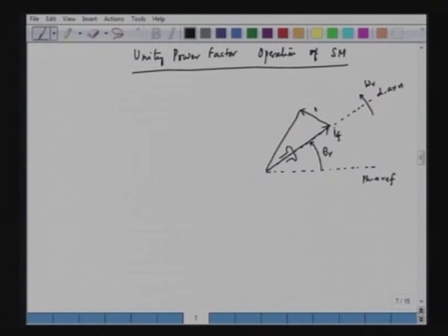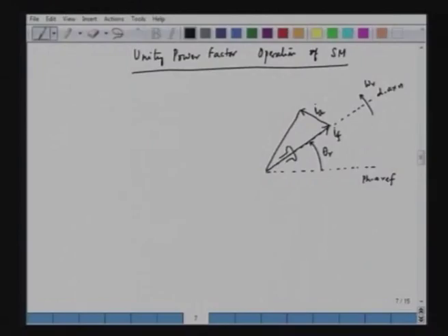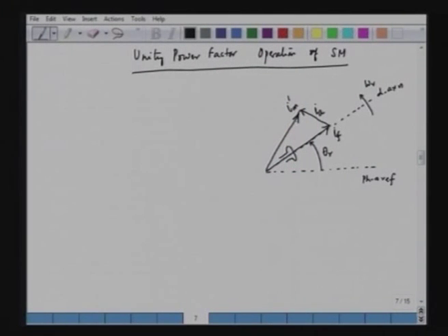This is armature current, we can call this IA, and the resultant of the field and the armature, in the machine we have two excitations, the field excitation and the armature excitation, is the resultant current, which we call the magnetization current. So, this resultant MMF or the magnetizing current is Im prime, which is the resultant of IF vector and IA vector. Each one is a vector, because MMF is a vector. So, we can represent each current as a vector. So, this Im is a vector which is along this direction.